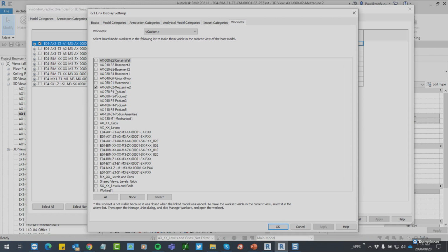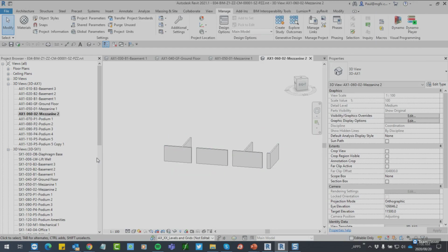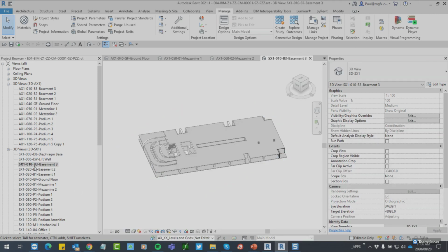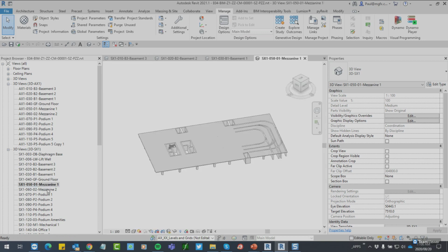So we can pick up on level mezzanine 2 which mezzanine elements are clashing with piping or with electrical. So it's per level. And then one can extract that. On the structural side, it's the same. So each level is isolated through work sets.